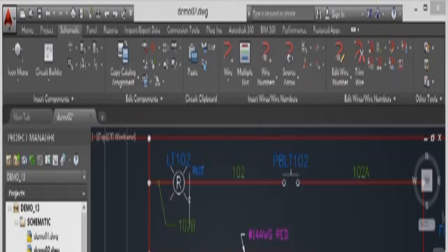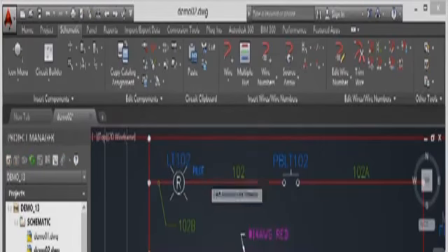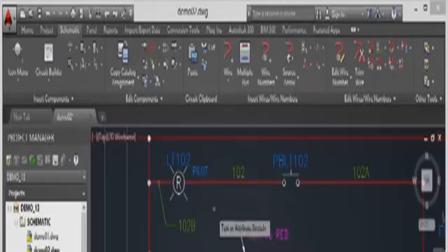You can do this using the right click menu. So I'll select LT102, right click, attributes, and I can stretch the attribute text. And again, it's just click. Keep clicking and checking the command line until you get it back to the 0.95. Press enter to finish. Job done. So we're back now to the default settings that we had before we did the stretch and also the squeeze attribute text in your AutoCAD electrical drawings.